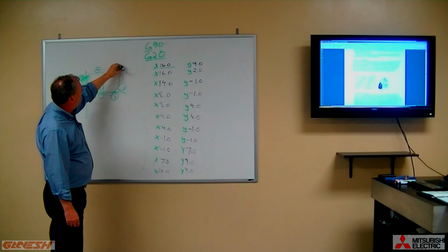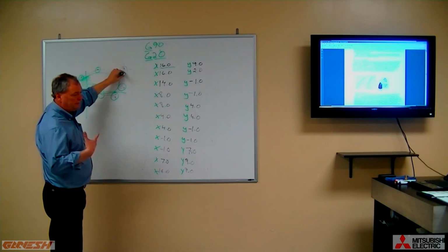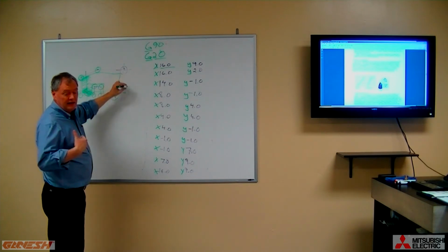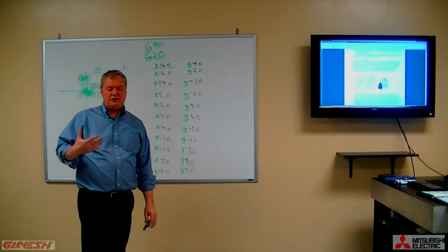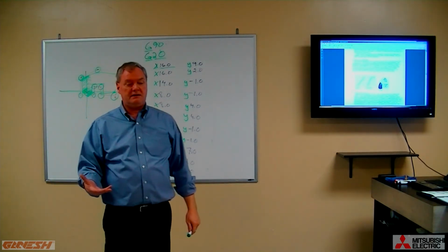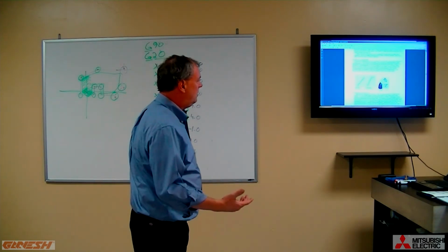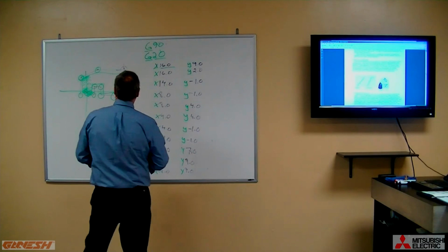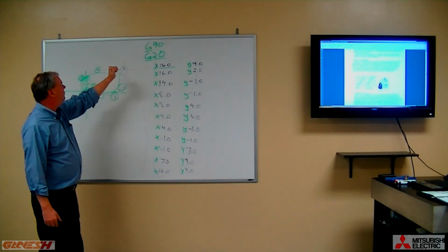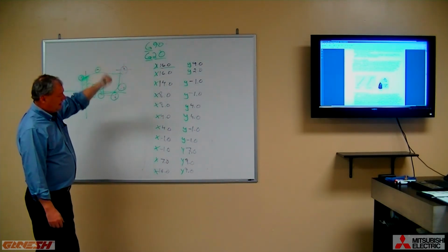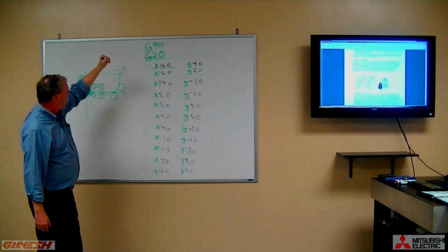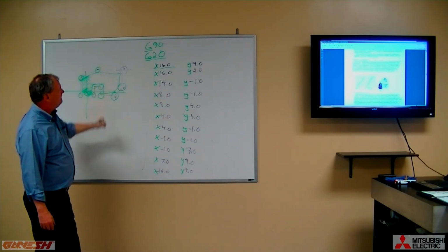So what we want to do is have the tool advance at a predetermined speed that we choose. And we express that speed in terms of a feed rate per minute. As opposed to if we wanted to move this tool around this profile at a rapid, very quick feed rate, being that we're up in the air and not cutting material.